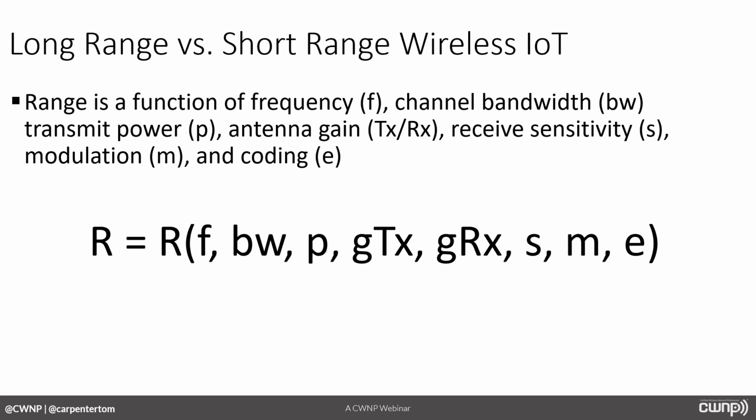And one of the reasons for that is the end devices are often these little devices. We want them to fit in little spaces. We don't want them to take up too much space. And they may have a PCB-based antenna or something like that, or they may have an external antenna, but it's much smaller. So the antenna on the end device is usually, not always, especially in outdoor agriculture and things like that, but for indoor deployments, most certainly, we tend to see shorter antennas on end devices, longer antennas on gateways.